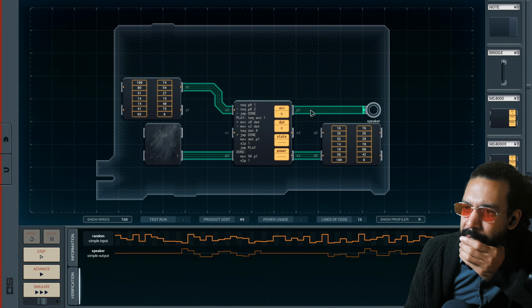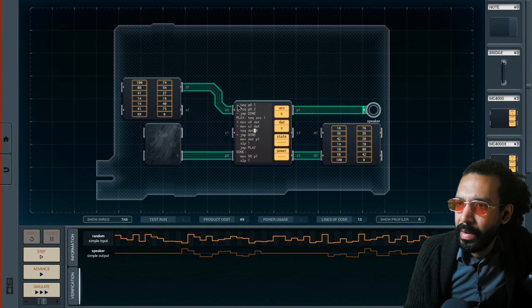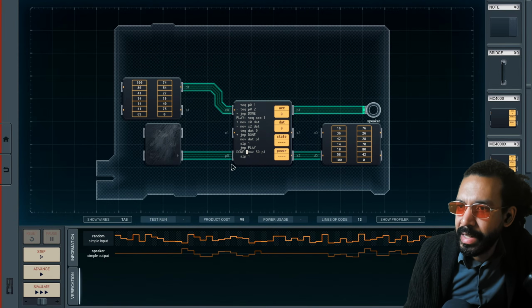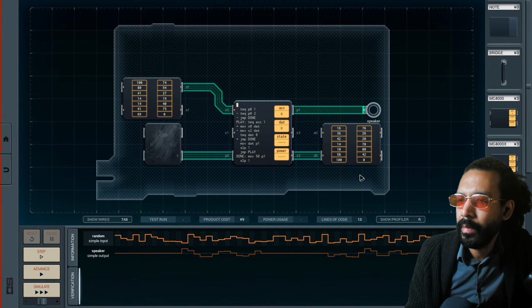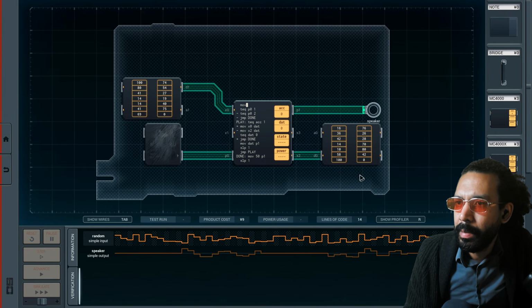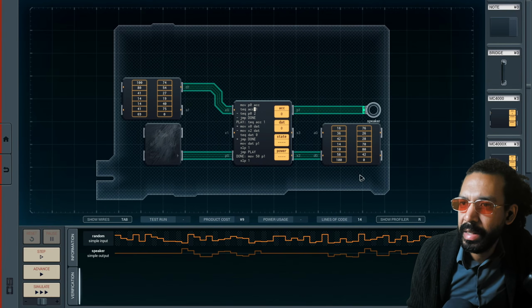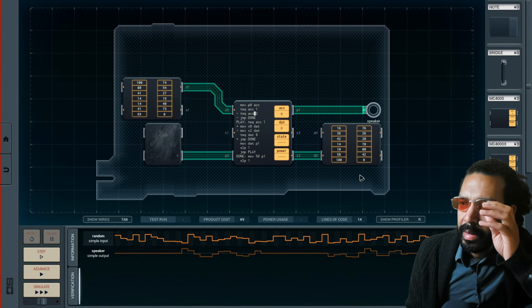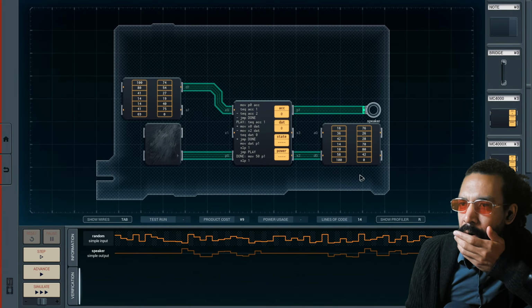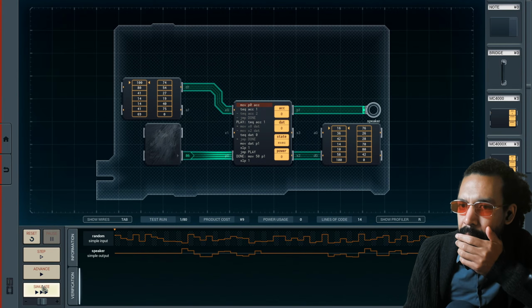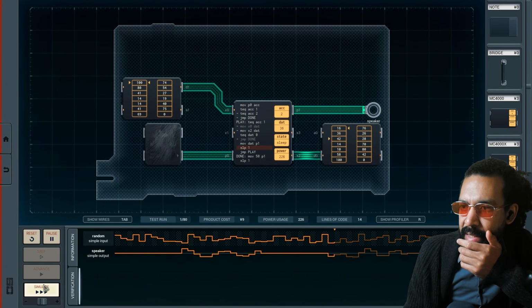Can we read from P1 that we just wrote to? I'm not sure about that. Alright, we're still pressed for lines here, but we'll make it work. So first we're going to move P0 to accumulator, and we'll just test the accumulator. And this is me doing an OR. And if neither of those are true, we jump to done. Otherwise, we go into the play. Okay. That should fix that.